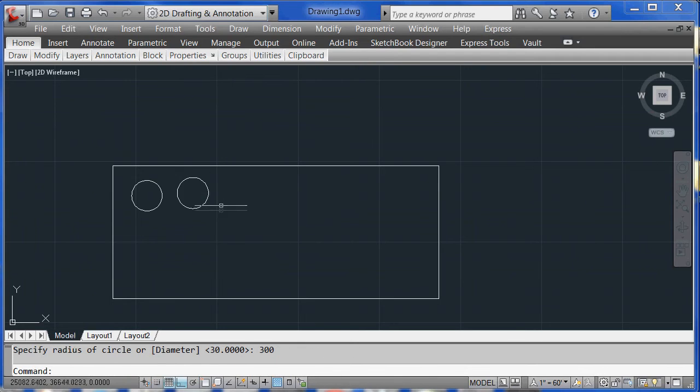Okay, that's better. Alrighty. So what you're going to do is create your drawing to a relative scale, but depending on the units that you start off with are the units that you're going to have to deal with when you create your radiuses. So when you first initialize your drawing, and if you initialize it correctly, you should be okay for the rest of the drawing. So these are, like I said, large circles. Okay, so now, in a quick review, we've covered the line, the erase command, the trim, and the circle.